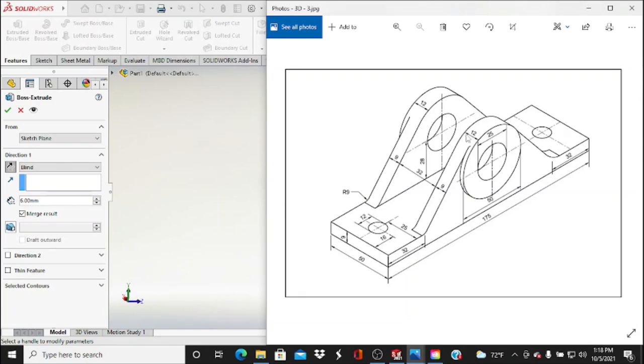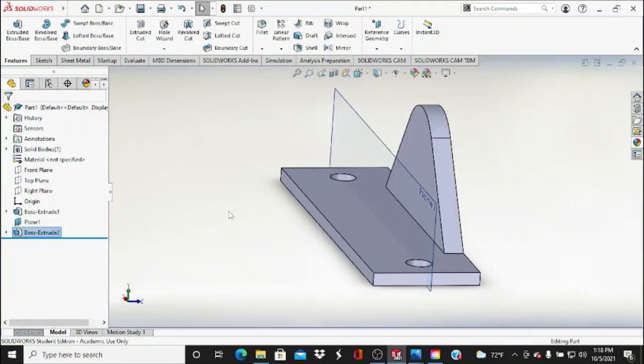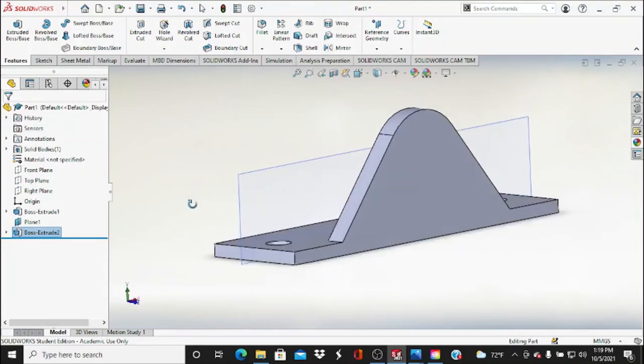We thought it was going to be about 12 millimeters, but that's from this base to the exterior of this circle right here. Right now we could choose the 9 millimeter thickness. That's the true base. So right now we're at 6. We can type in 9, enter, and there we go. And we got to press check. Okay, and we're good. Now we got our shape right here.